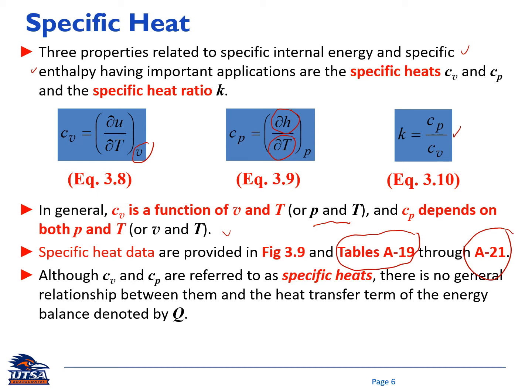So people represent it with Cp or Cv to show how much is the Q so that delta T equals 1. If a material has a higher Cp, it means it requires more heat to increase the temperature by 1 degree.